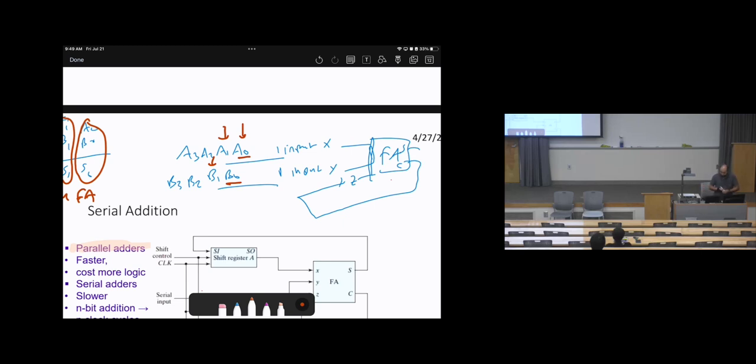Basically, we will shift, for example, shift right. So after the first cycle, it will be A3, A2, A1, then A0 will be here. And the same happens for B: here is B1, here is B2, here is B3, then here is B0. So we just shift left or shift right. Then after making these shifts, we can go to the next cycle to make another round of addition.